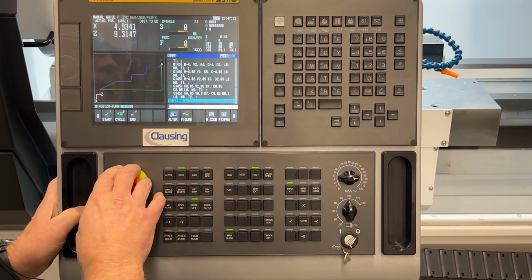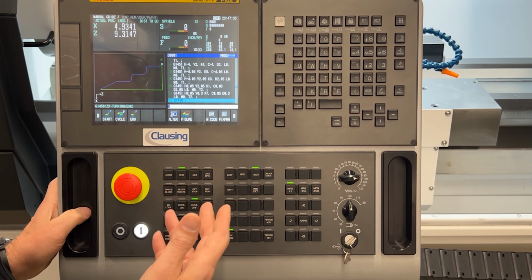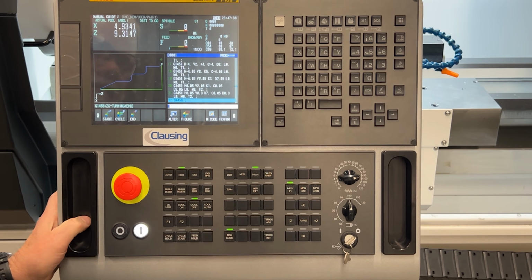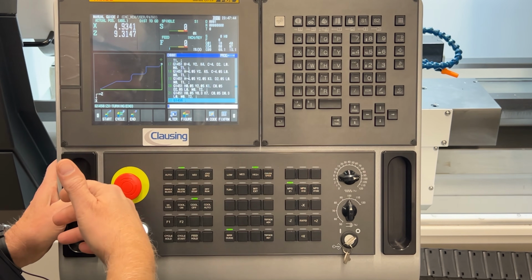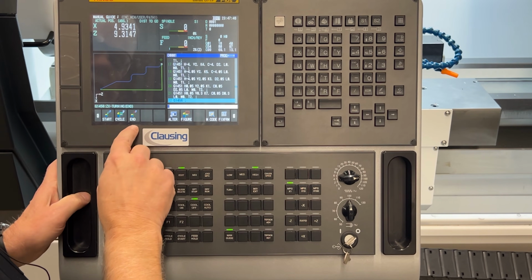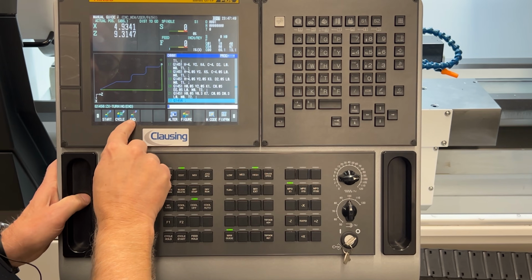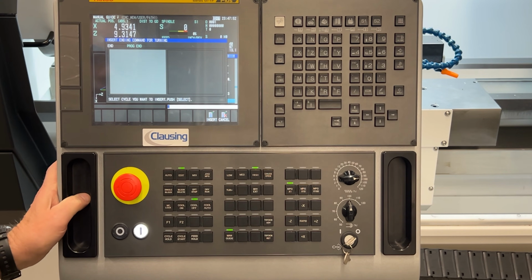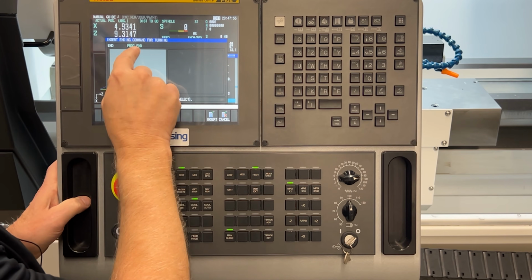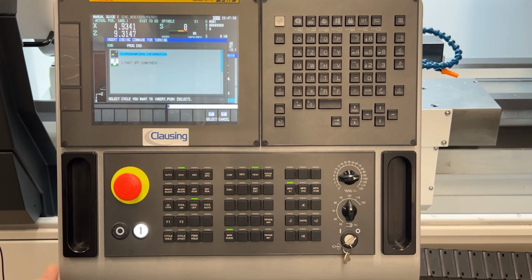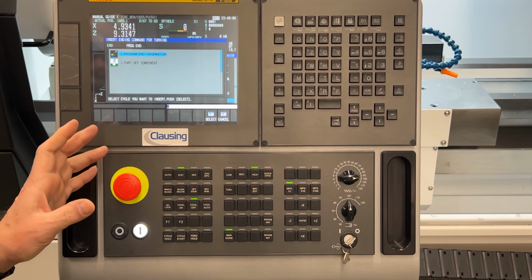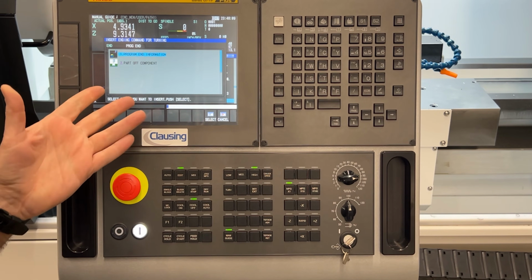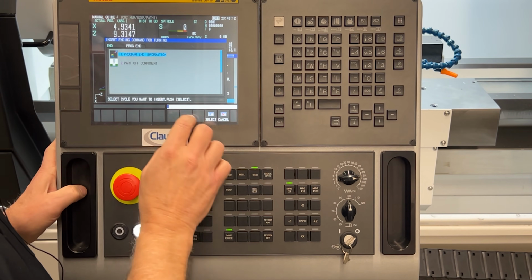So once that's inserted into the part program, that was the only thing I was going to do with this part, just a rough and finish pass on it. That's just an example, that way you can incorporate this in any part program. Now I'll select the end here, which is the end of program. So you got end, and then I'm going to go over to program end. Again, this is information that was developed by Harrison just for their controls. And so I'm going to hit program end, select that.